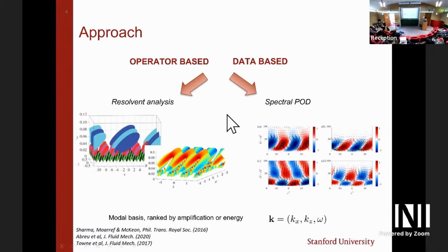Over on the left-hand side, what we call resolvent analysis. It has a long, long history, and Peter and Clinton Henningsen had a discussion about this for transitional flows. We use the resolvent linearized operator to understand what modes are naturally amplified by the system. And they're amplified in a forced sense, so we're talking about the pseudospectra rather than the eigenspectra.